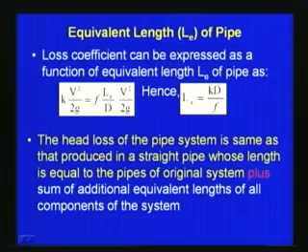Like this, for various valves, various junction T's or various gates, depending upon the type of material, according to the way of manufacturing, and how we give the connection between the main pipe and the valve or the fittings, this K value will vary. Most manufacturers specify the K value for their products depending upon the material.